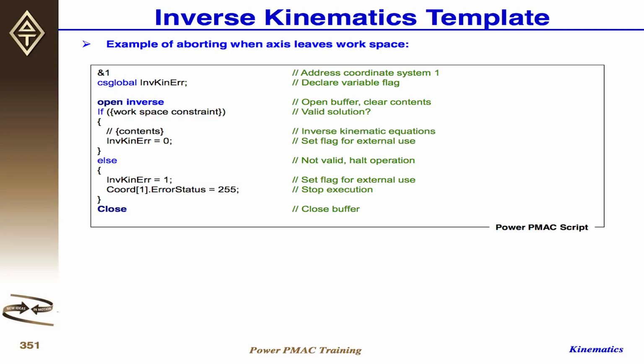Any questions so far? So kinematics is not really hard. It's the same concept as the axis definition. It's just we don't have a linear relationship, so we cannot put just a matrix over there to do the converting between the axis and motor. Okay? So it's your responsibility to make sure that whatever you put in here for the content for inverse and whatever you put in for kinematics are one-to-one mapping.